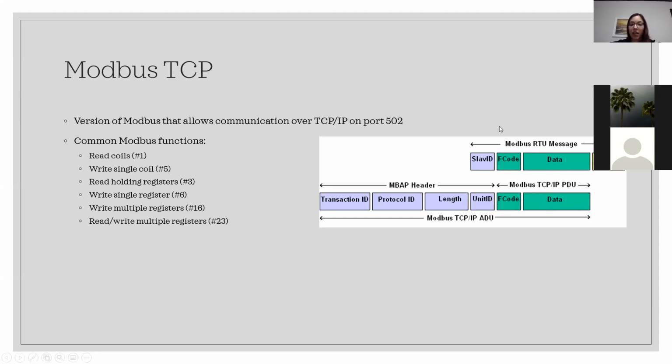Modbus TCP communicates over port 502. It does not authenticate. There's no authentication mechanism for Modbus. So any person can set up a Modbus client and communicate. It'll accept anyone's messages and believe them to be valid. That's a major, major issue with Modbus as a communication protocol. And you'll find that's very common for ICS protocols.